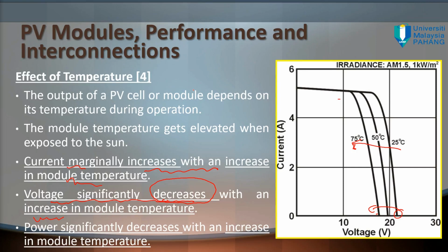But for the 4 season country, when the temperature is lower but the irradiance is higher, it will cool down the cell temperature. So the cell temperature can be suppressed to lower, maybe around 25 or 26 degrees, the ideal value, at the time it receives a higher irradiance. So at that time, mostly in those seasons, the PV modules perform very well. That's the concept.